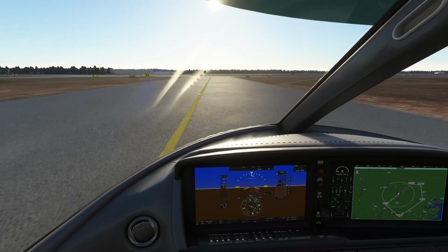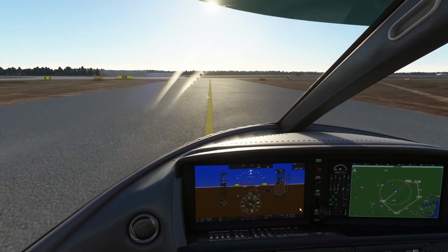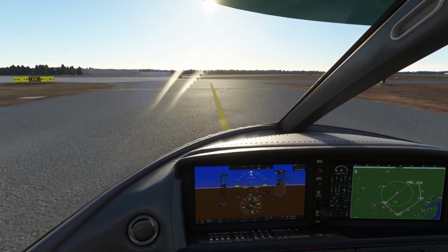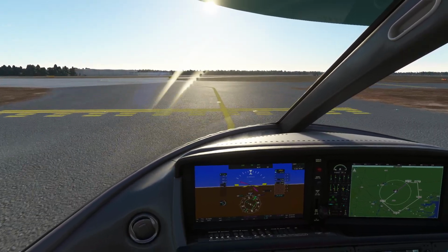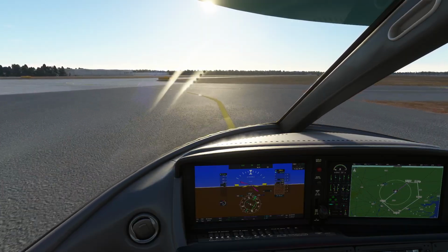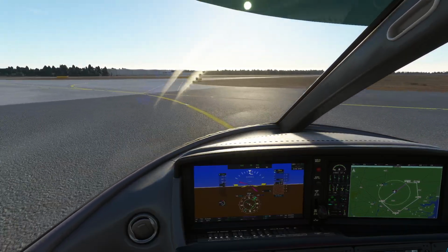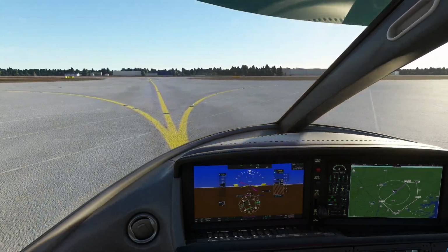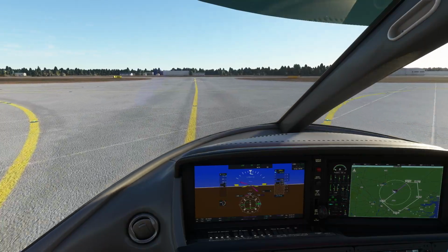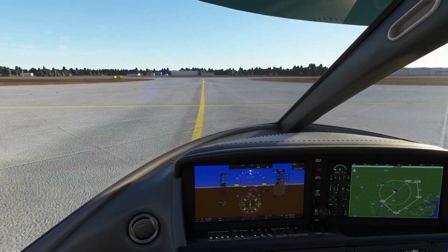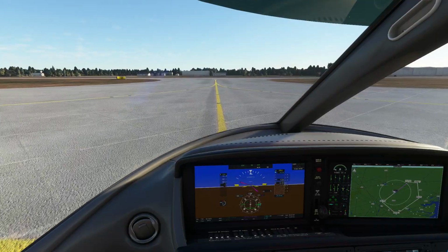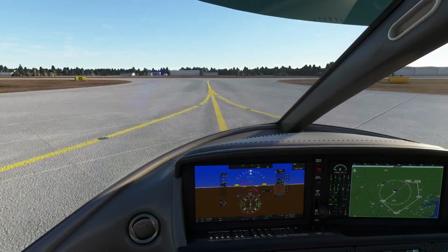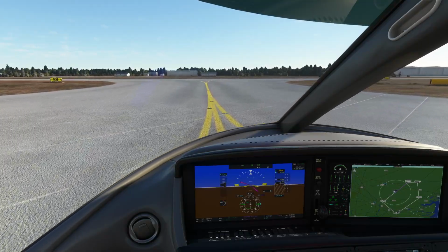So yeah, hopefully showing you all those different modes and how you can interoperate between them, of reverting to heading mode and GPS mode, and then localizer or nav mode using the radios. You just naturally switch between them during the flight, really. And obviously while you're en route you might be using GPS all the time, but once you get onto finals you'll be switching over to radio, so you probably want to get your heading ready beforehand, so you can, in the interim, have heading mode on while you sort the ILS out.